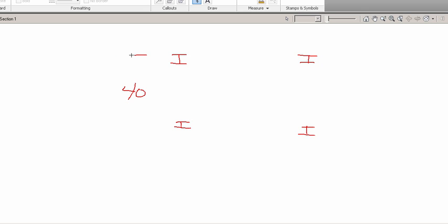And typically, buildings, that's the wrong way to do a dimension. Buildings can space things from center to center or from outside to outside, just kind of depends. You just need to always watch where your dimension line touches. And then of course we've got a center line right here going between that beam, center line right here between this beam, or I'm sorry, column. Again, these are columns.